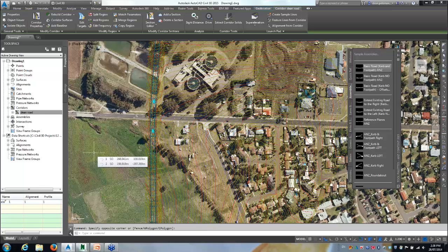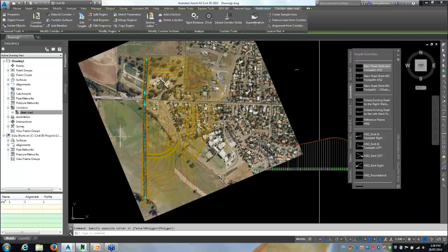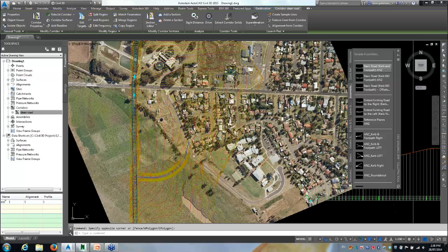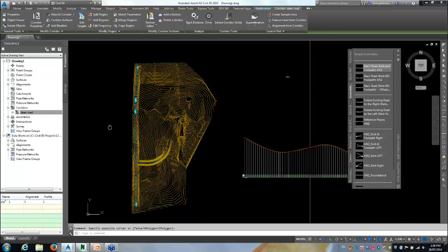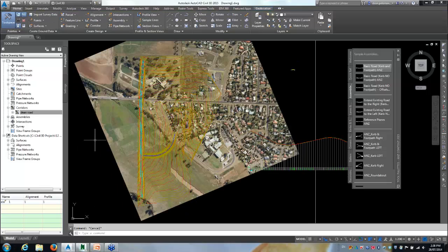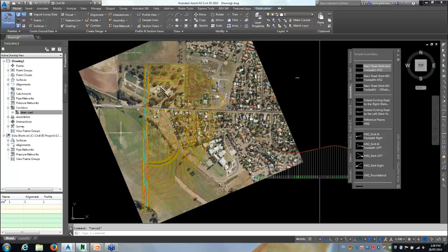There's one more thing we want to do. We want a ground surface that includes the datum surface of that corridor. So when we see it in NavisWorks, we're going to see our corridor on top of the ground surface as it's being built. So I want to incorporate this corridor into the surface that's being used in the NavisWorks drawings with NavisWorks files. So in order to do that, we'll first of all make a datum surface out of the corridor.